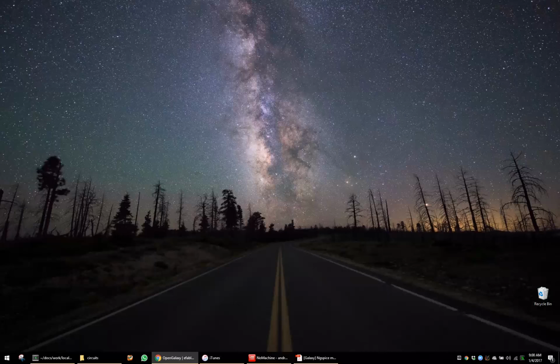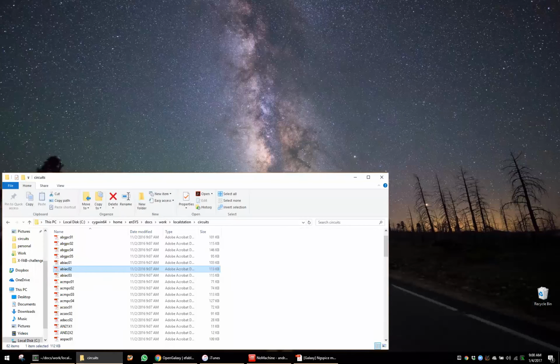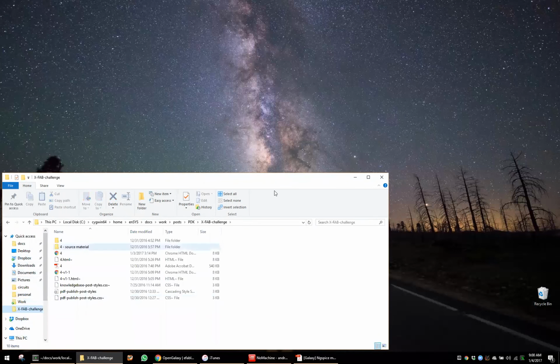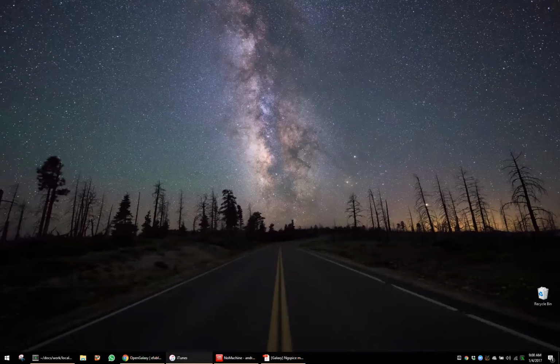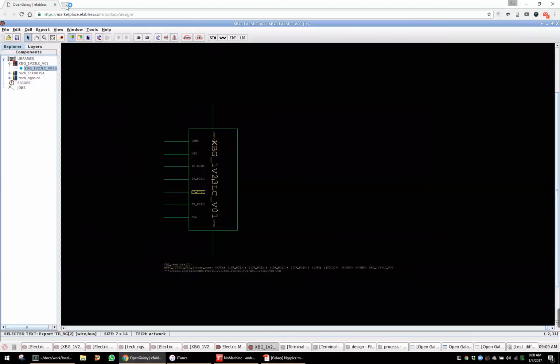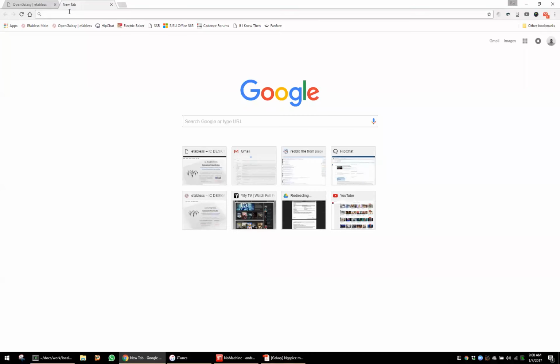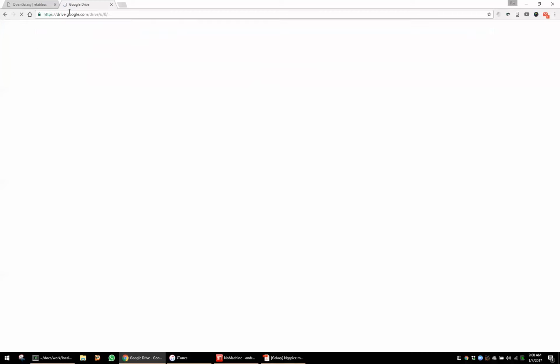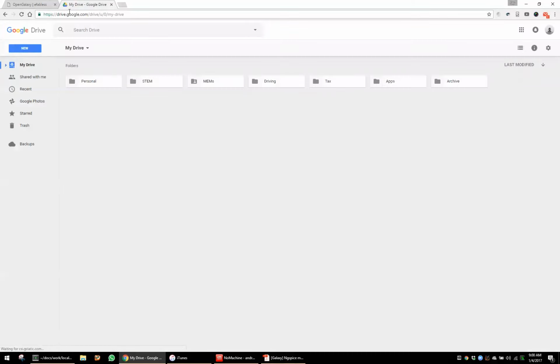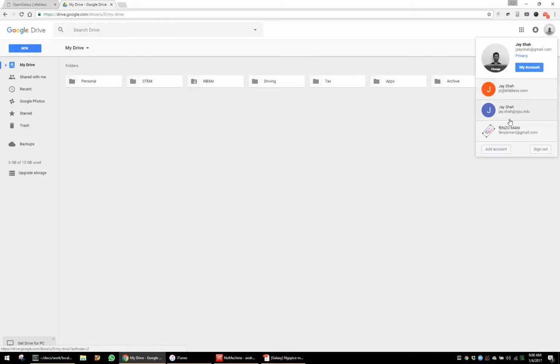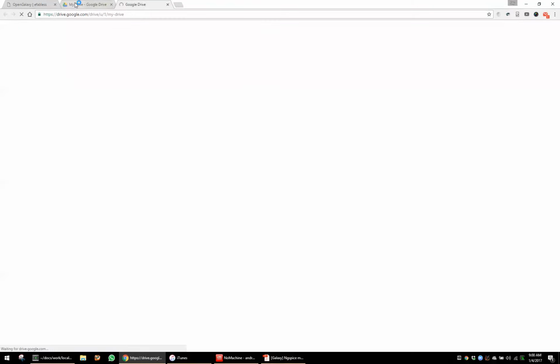A question about the resistors to use in the schematics. I am using the well resistors, which have the biggest resistance per square. But when you send the email, there are some definitions about the minimum sizes. I have checked it with XFAB.